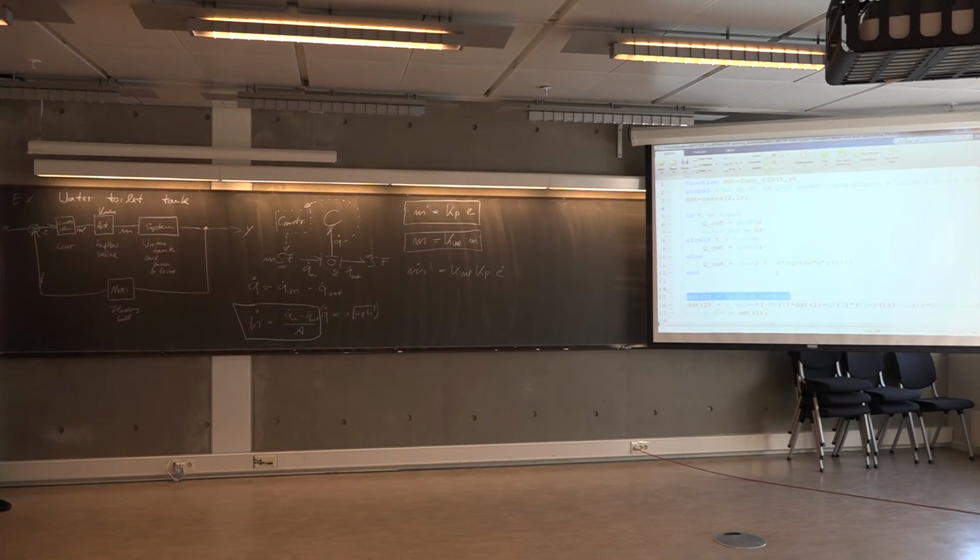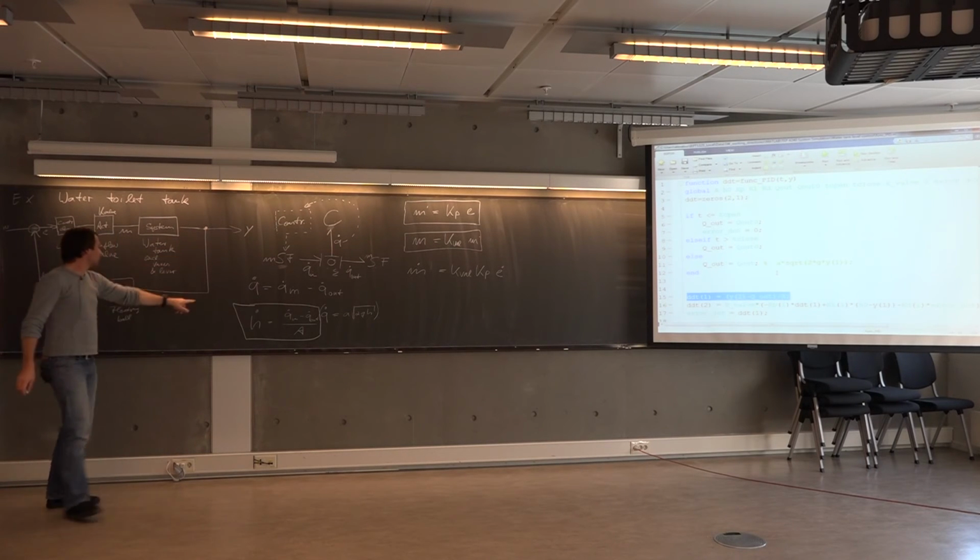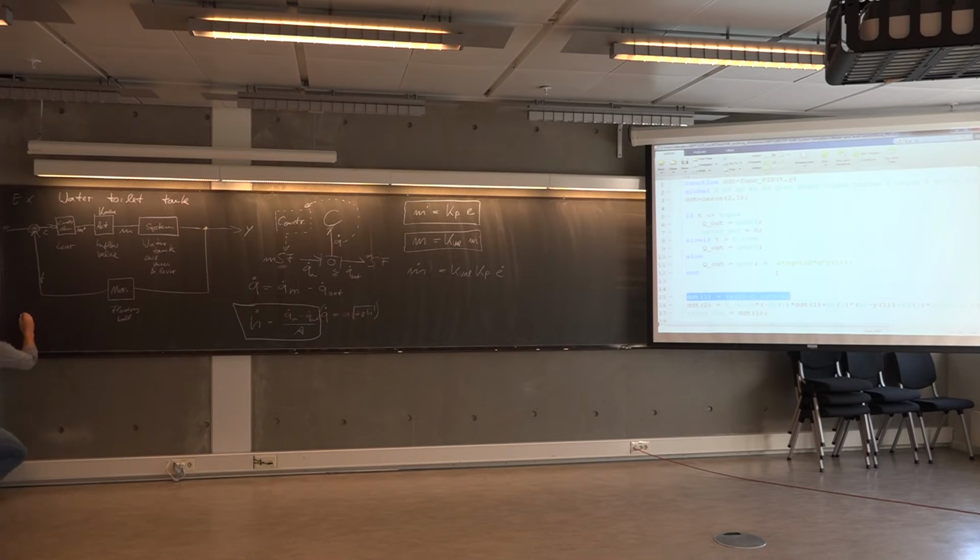This is because, as you can see from the control loop, the error is the reference value minus f. Now, if the reference value is constant and you take the derivative, it basically means that the rate of change of the error and the rate of change of the water level height is equivalent, which is why we can use it in this manner.